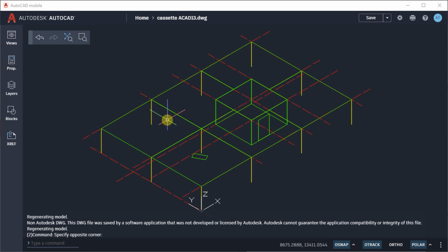So just to recap, the yellow lines are standard lines. These will be the columns. The red lines are lightweight polylines, so the normal polyline definition. These are grid lines. And the 2D polylines or heavyweight polylines are the green that I'm using for the floor slabs, the penetration, and the core walls. So that's my AutoCAD subframe starting point.